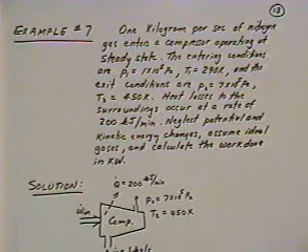The temperature is 290 degrees Kelvin, so this is again sort of an atmospheric condition where you've got nitrogen entering, and you're exiting at P2 of 7 times 10 to the 5th pascals, and so you've got a compression ratio here of about 7 to 1 on the nitrogen. The leaving temperature is 450 degrees Kelvin, and although one of the assumptions normally made for compressors is that there are no heat losses, in this particular case we do have heat losses that occur at the rate of 200 kilojoules per minute to the surroundings.